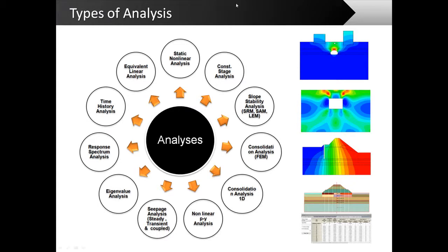These are some of the analyses that can be performed in the software. As you can see, we have static nonlinear analysis, construction stage. Also, we have different dynamic analysis such as response spectrum and time history. We also have consolidation analysis and, for example, PY nonlinear analysis for the foundation module. We also have seepage analysis, and we have slope stability analysis, as you can see here.